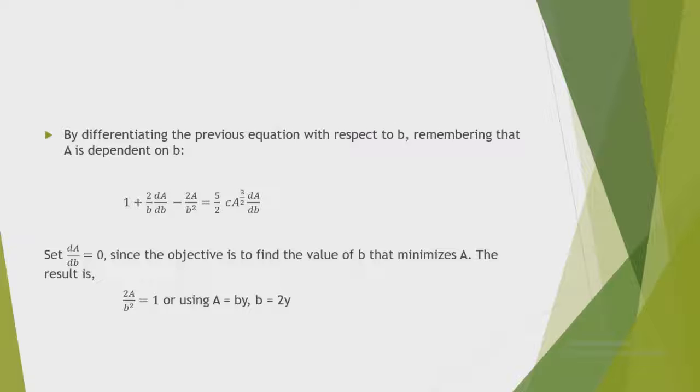The optimum criterion based on the flow resistance cannot always be used, and in fact may be less significant than the other design factors. Additional aspects to be considered are the type of excavation, and if the channel is unlined, the slope, stability of the side walls, and the possibility of erosion of the bed.